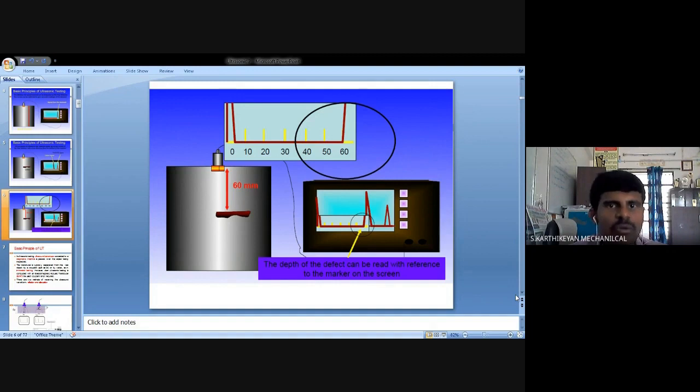We simply find out whether the workpiece is defective or not. That's it. But in ultrasonic testing, the flaw is found inside the material. So we have to monitor deeply how far the defect penetrates the material, to decide whether it can be used in further applications. For the final decision, we have to take the exact measurement of the defect.